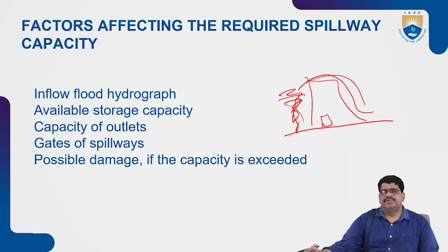That can all be designed as per the requirement and availability for the dam's construction, and the designs will be given by experts as to how much is required for the free flow of water through the dam without any obstruction, without any damage to the dam. That's why we are going to provide the spillway, and we also have to handle the excess water when flowing. Energy dissipators also, as we discussed, are very important so as not to damage the structures of the dam.